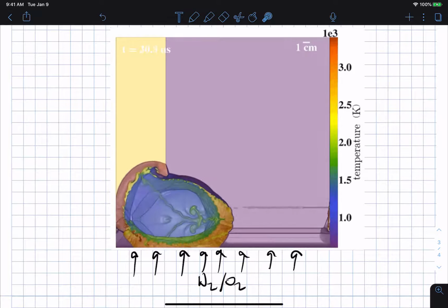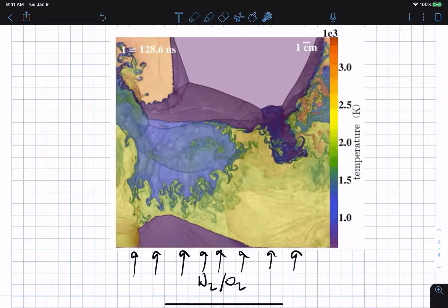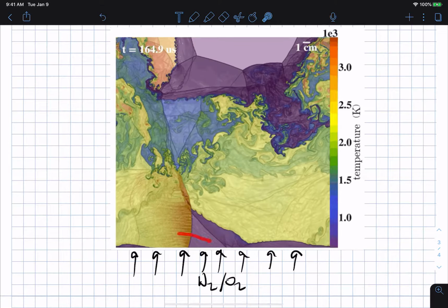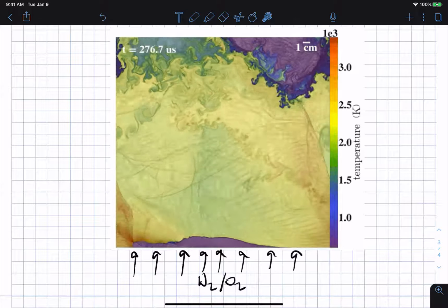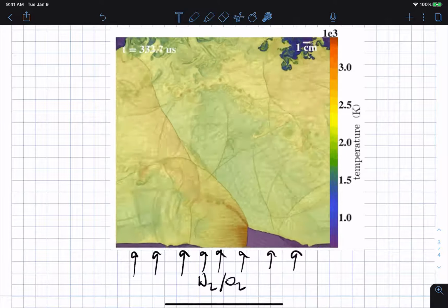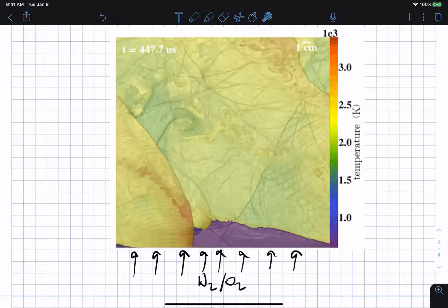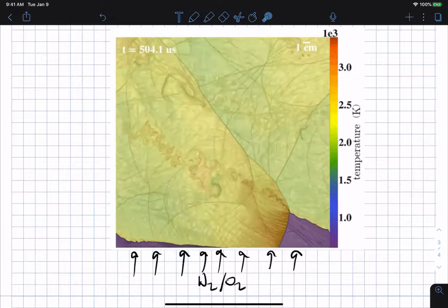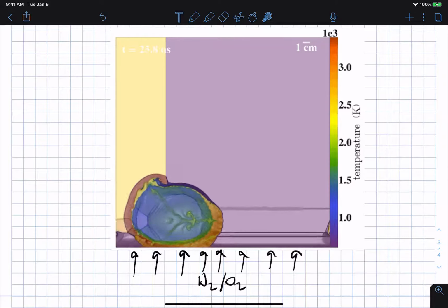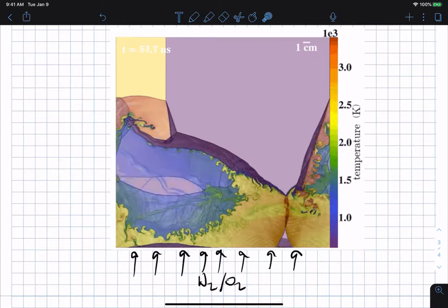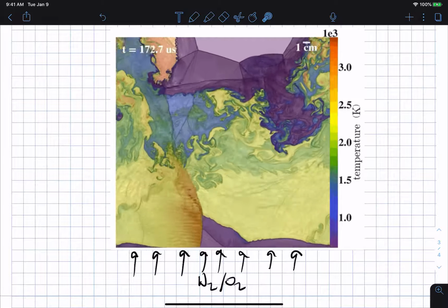And basically, the hydrogen and oxygen gets injected into this region here where they ignite and burn. And this wave, and I'll let it loop through again, this combustion wave, it's not a flame, it's called a detonation. And so this here is a detonation wave that basically travels around and around, and engineers actually make these devices. And why they're interested in intentionally triggering a detonation or an explosion instead of just having a flame is if you think back to your thermodynamics when you're comparing the Otto cycle to the diesel cycle, for a given energy input, a constant volume heat addition process was usually more efficient.